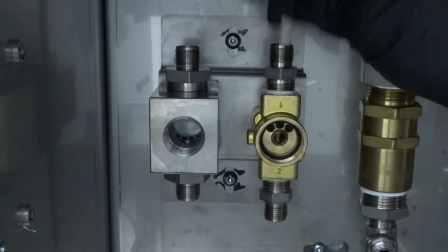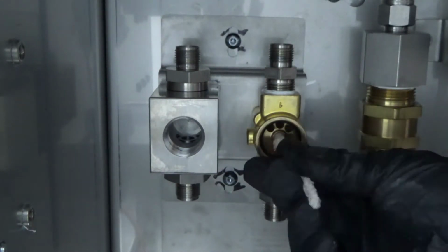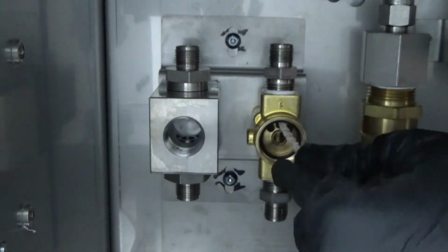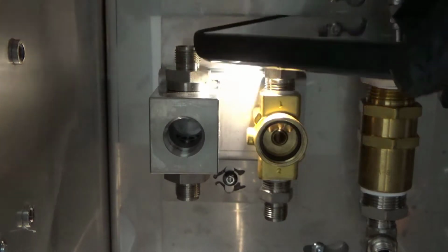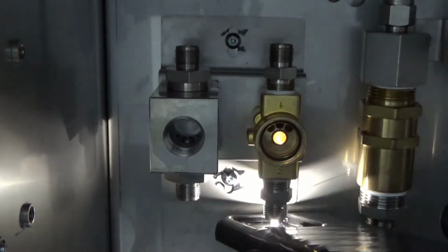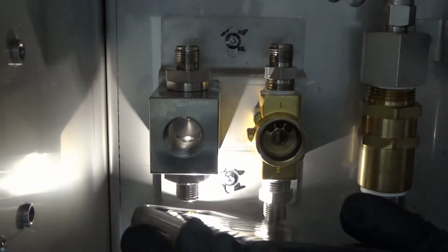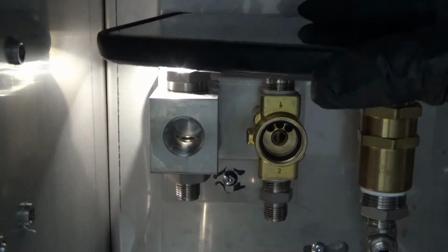Once we have snapped our photos, we will want to use our pipe cleaner to clean the exhaust solenoid and moisture sensor blocks. Once we have cleared out both the moisture sensor block and exhaust solenoid, we will want to shine a light through the top and bottom of both components. This will help verify that there is no more debris or clogs in these components.